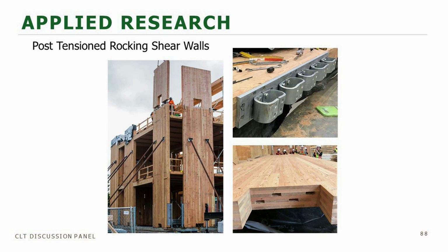Yeah, that is pretty unique. I was just going to add, I should have added, that is certainly not the standard exterior application. We'll typically see some type of exterior insulation on the outside of the wall. In the 2021 IBC, there is a requirement that there is a layer of 5/8 type X on the exterior side of the CLT. Obviously, that would be inside your moisture barrier, but that's just for additional exterior fire protection. So the exterior of these buildings can range.